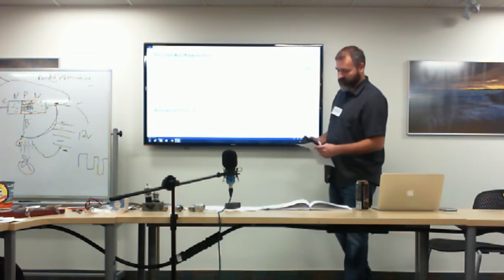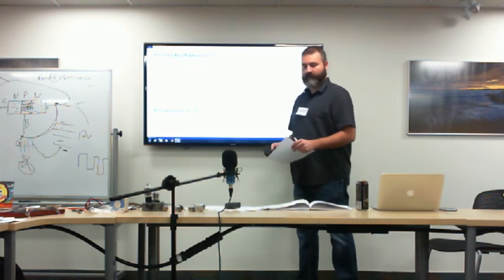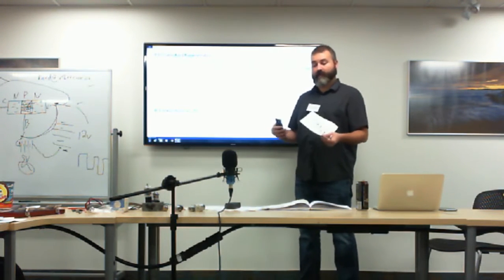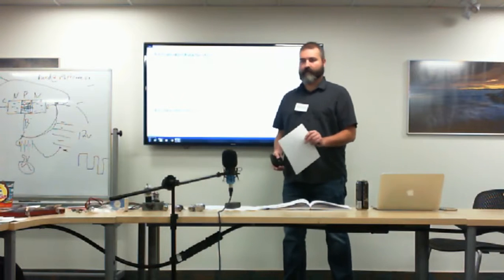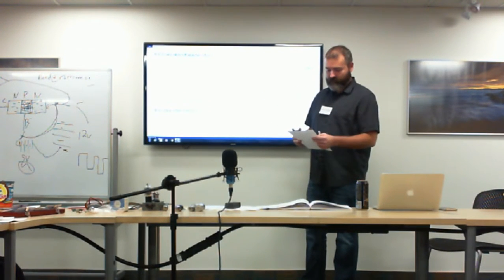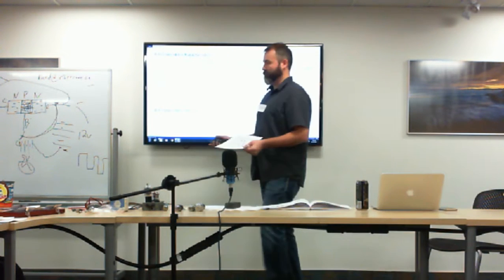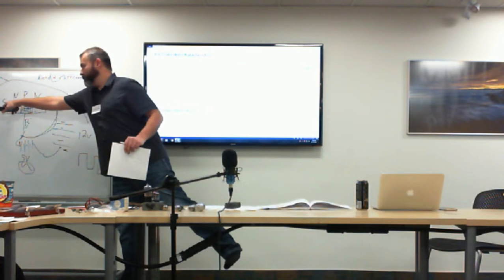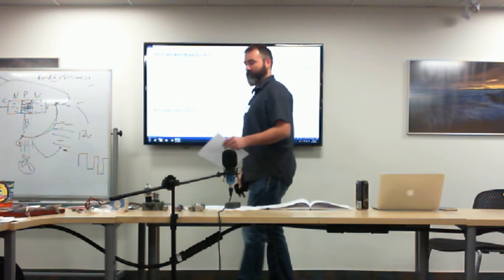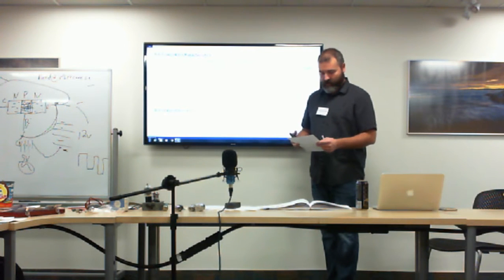The maximum voltage is the maximum operating voltage that may be safely applied. So the maximum voltage would be the amount you can safely use without causing it to overheat. In some cases, you will still require a heat sink, but they'll list that in the sheet. Maximum current is the maximum amount of current the collector can handle, and the collector again will be on the outside. It is how much power, the large power, you're going to be controlling through the transistor.